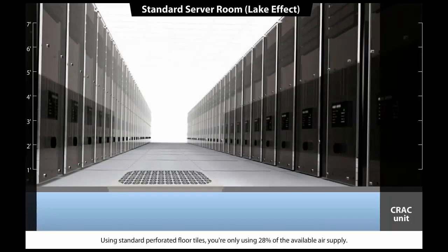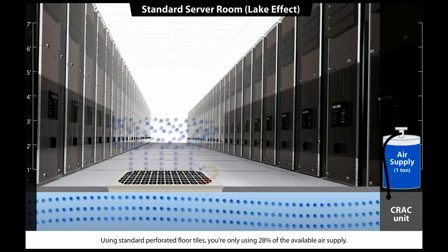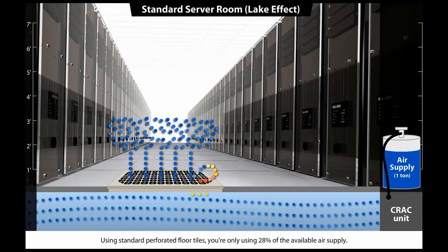In the modern data center, floor tiles play a critical role in moving air through the subfloor plenum and dispersing it where it's needed in the crowded IT rack environment. The problem is simple. Servers and data equipment are often exceeding the recommended air inlet temperatures set by the ASHRAE standards body for recommended server inlet temperatures.